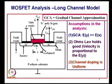You solve the Poisson's equation along the x direction, that is top to bottom. I am marking is non-conventional, y is in the horizontal direction, x is in the vertical direction. Okay. So, you can solve the Poisson's equation in one dimensional direction, because you consider the electric field only in the E x, because E y field is small. This assumption will fail when you go to high fields, okay, in the y direction. That is where you have to think other methods of solving it.